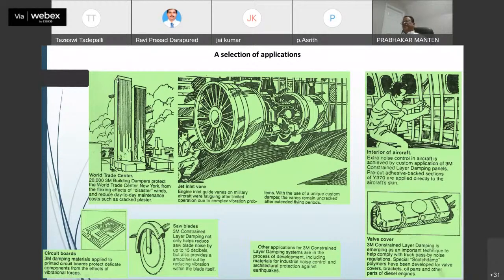You cannot apply it effectively where the maximum deflection is; it is the curvature that matters. At the free end there is no strain energy in a cantilever beam. In the fundamental mode, if the beam is excited in the second mode, you apply it at the maximum curvature, not at the node point. Again, that's the importance of the node point. In the second mode there will be a nodal point here when it vibrates this way. So arbitrarily applying damping treatments has no effect, because those regions are not being subjected to strain.